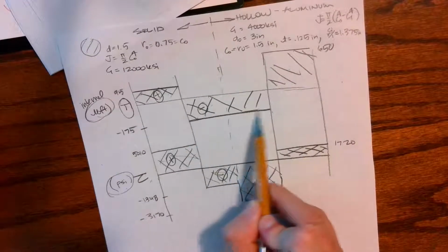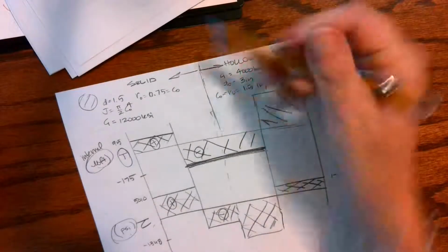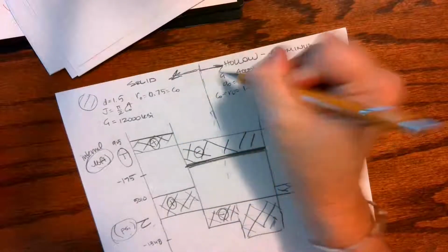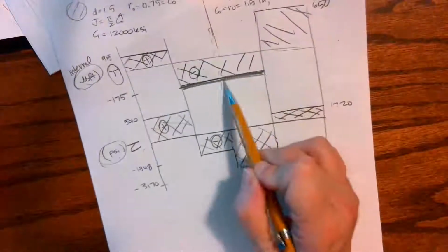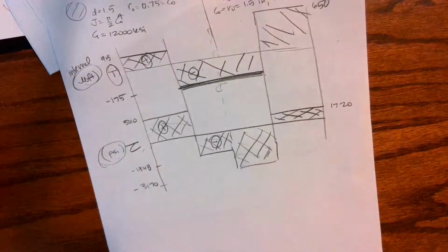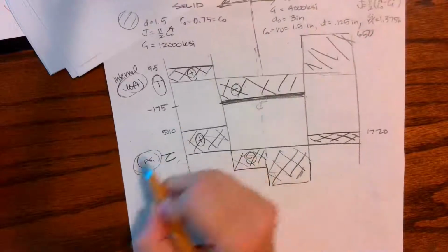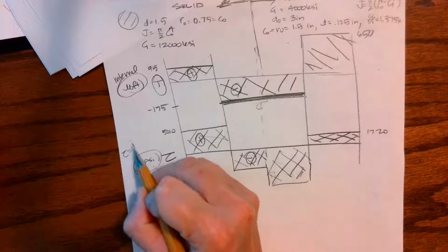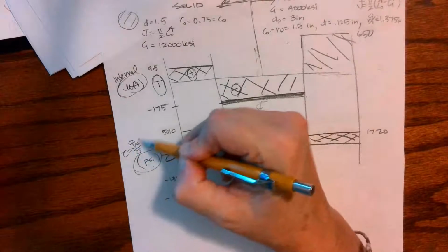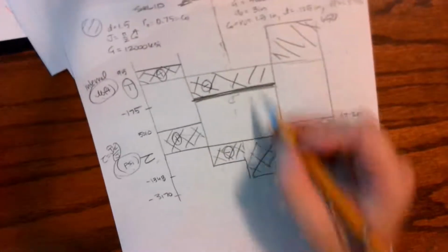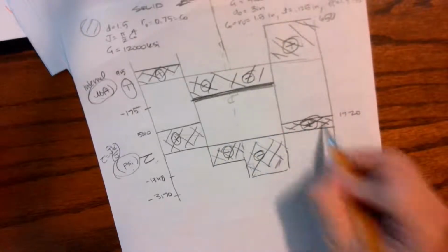And even though we have the same torque between these two gears, because I have two different materials, solid this way, hollow this way, aluminum and steel, they may have the same internal torque, but they will have a different shear stress, because shear stress is a function of torque and geometry. So their torque is the same, but their geometry was different. And again, we have negative torque, negative stress, positive torque, positive stress.